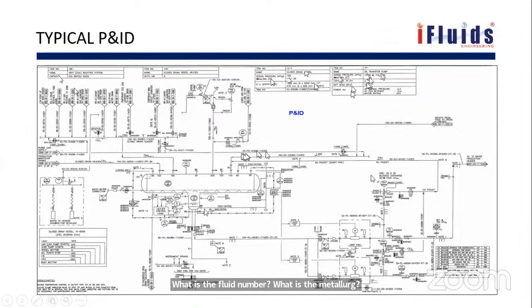Then if you see the control scheme, you have a level control here, you have a heater control here to keep the line warm, to heat the process. You have a level control here, it goes to this controller, and this output goes to this final equipment. So this pump is controlled by this level.